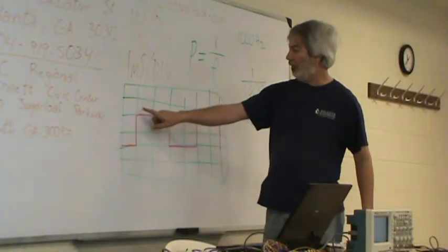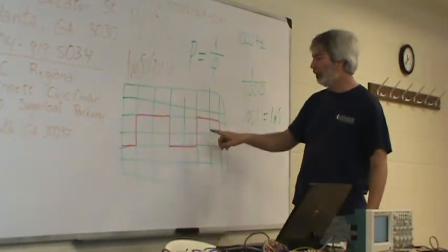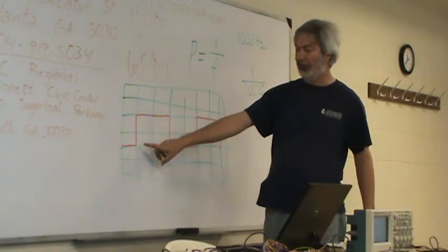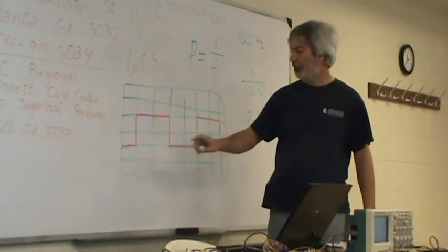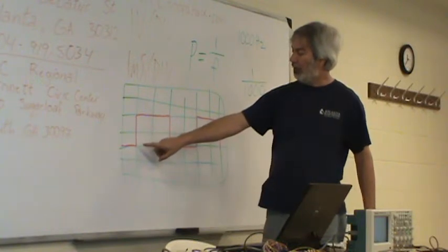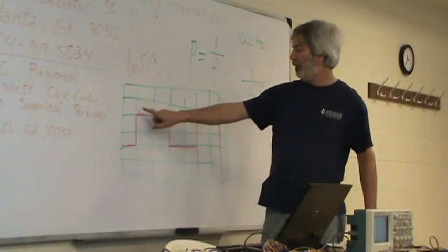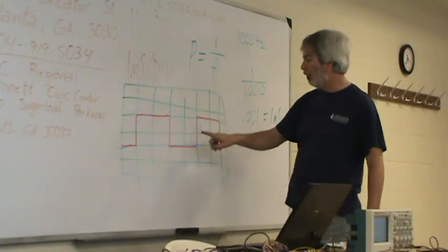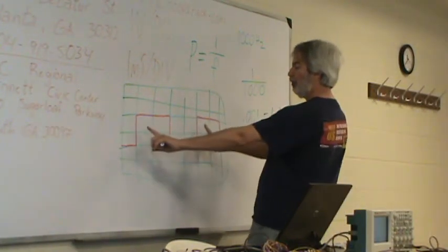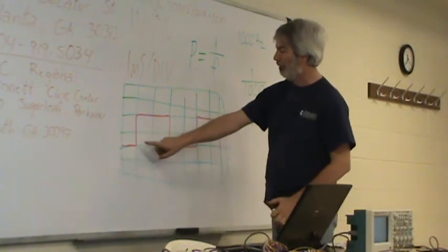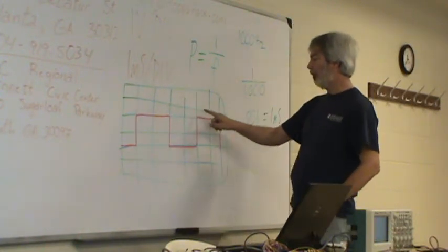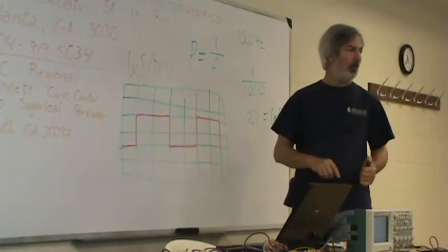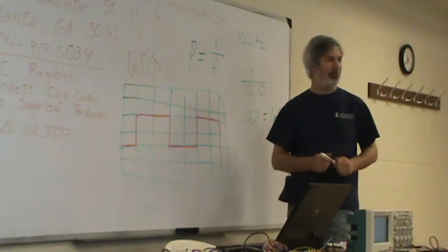The period of the signal is from one point back to a duplicate of that same point. So we're gonna take the rising edges, and we've got one rising edge here, one rising edge here, so this shows one full period of this signal. So we've got 1, 2, 3, 4 milliseconds is the period of our signal.